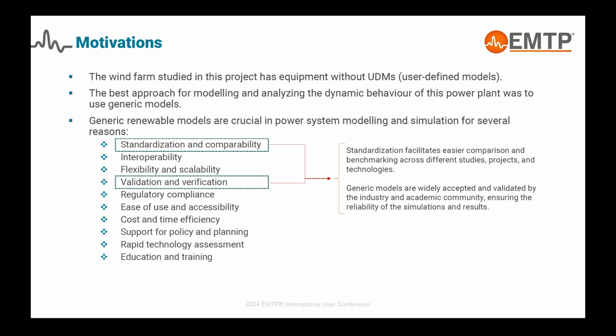This is not bad, because someone could ask me, why are you using a generic model? We know that when we use user-defined models, we can get more accurate results and represent our dynamic behavior better. But on the other hand, many utilities and ISOs still request both models. Today, if you are integrating a new renewable power plant, you need to provide the UDM and also the generic model.